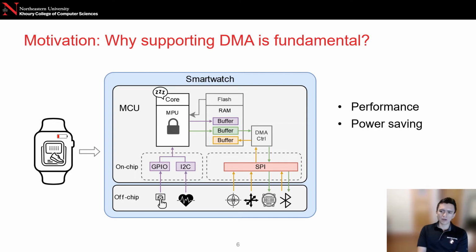Besides these characteristics, DMA has security implications. For example, a confused deputy vulnerability can be exploited to force the DMA controller to read and exfiltrate data from memory areas that were not meant to work with DMA. In general, if the DMA controller is compromised, it can read or corrupt any memory area because the MPU does not interpose any of these operations.